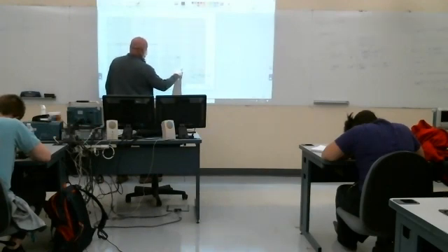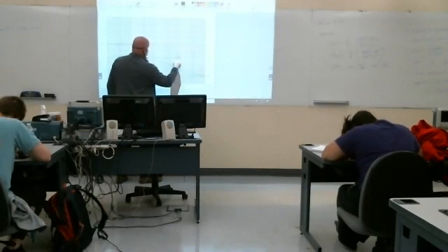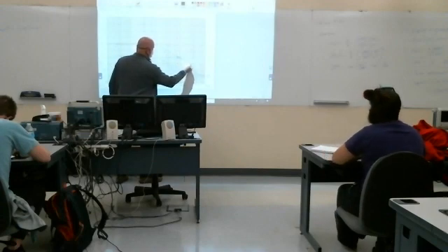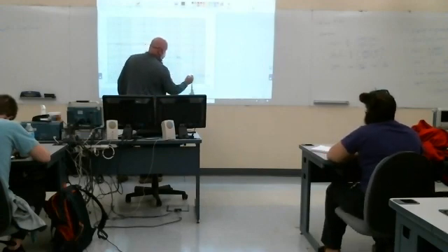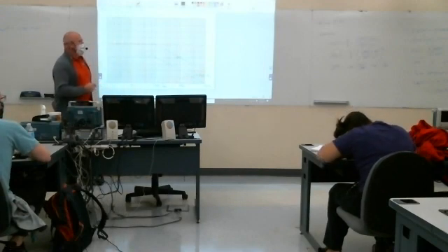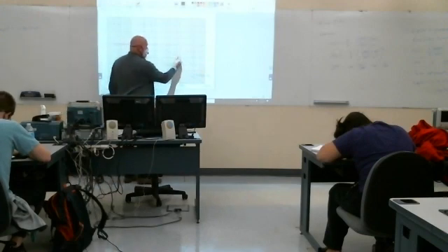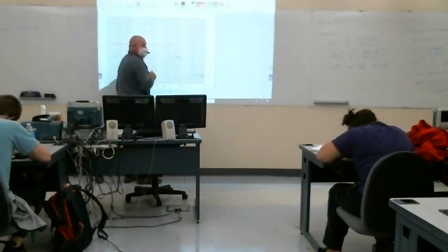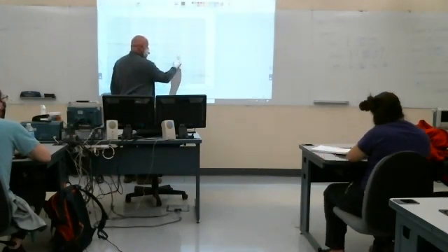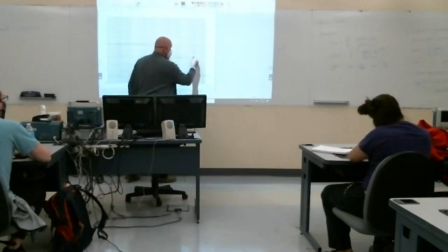It doesn't look parallel, but it should be parallel. This goes down 20, and that would end up right there. So I guess maybe I'm just standing too close. Now that would continue like that, except when I get to this frequency, it now goes up at 20 dB per decade. So to the right of this frequency, what's going to happen? It's going to level off, right?